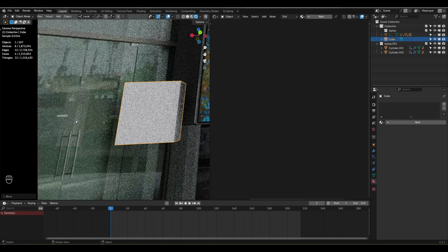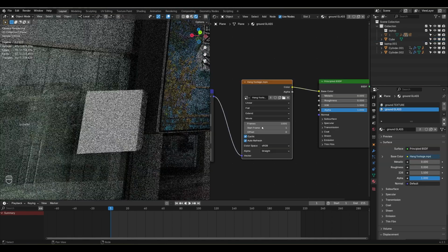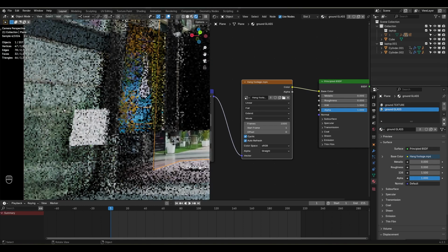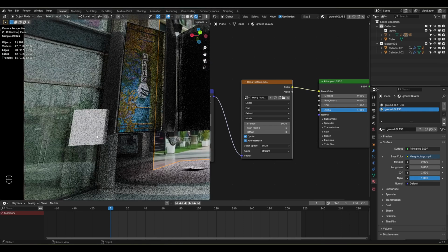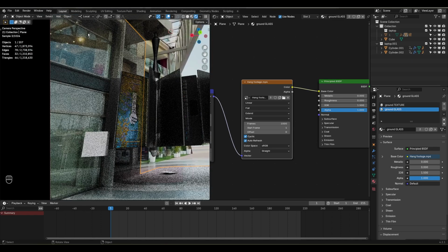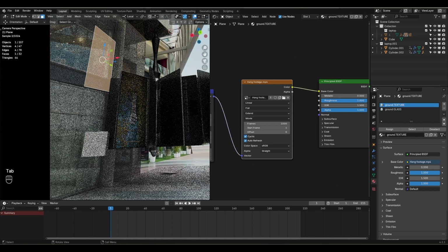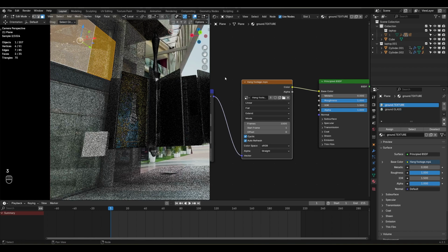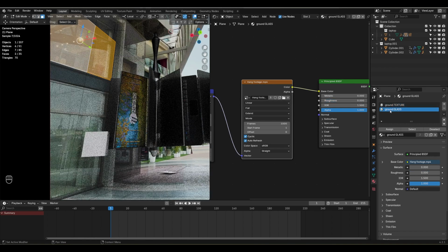If you will notice, now we are able to get the object reflection in glass. That way it will help us to get the reflection wherever this should appear. And I can also do the same for this part as well, if I want. So I can select these, Control R, and just add an edge loop and press 3 and select this part and assign this ground glass.